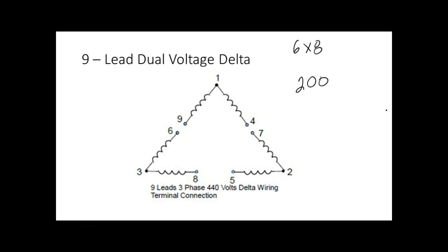Or we can run it through a bank of resistors, and then put resistors in series with it to start it up, which would drop some of the voltage when we try to pull all that current, which would put less voltage across the motor, so it wouldn't be able to create all that torque. And then it wouldn't tear up the load. So we did that for years. We had those big AC motors that we would put across the line. Or we could come up with a method.